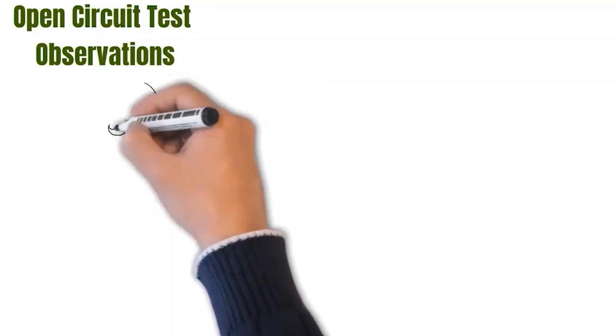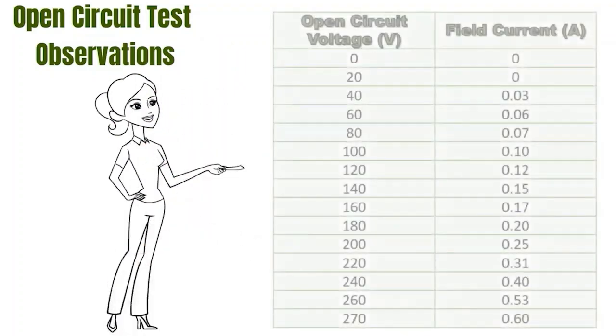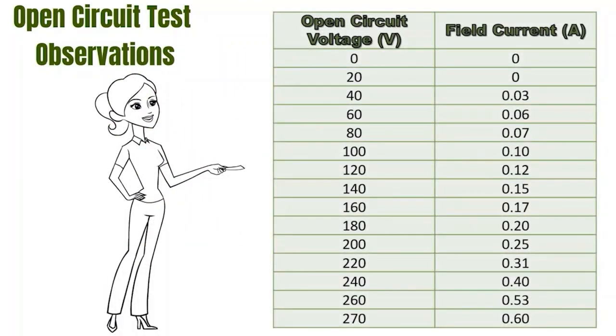Likewise, we have to increase the open circuit voltage 20 by 20 volts up to 270 by varying the field resistance, and take the ammeter reading at each step. So these are the practical values obtained in this open circuit test.